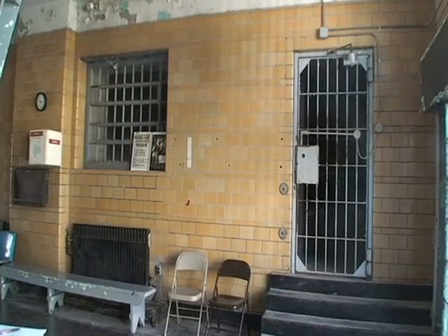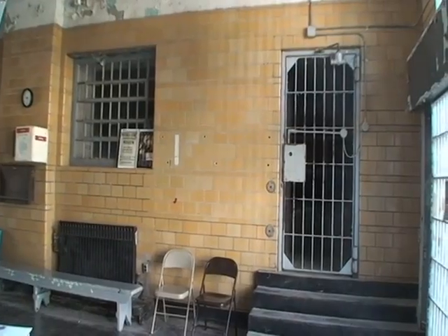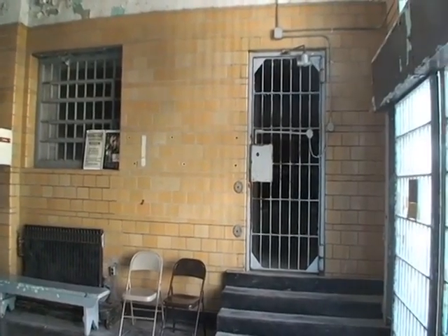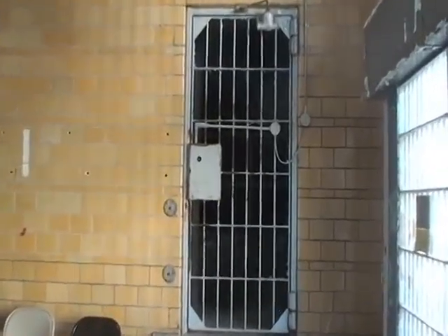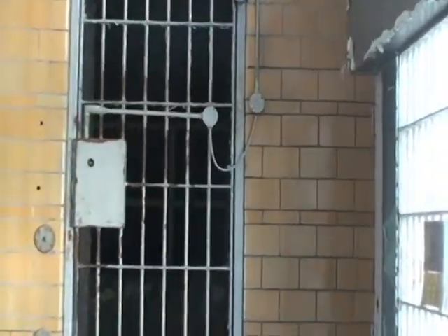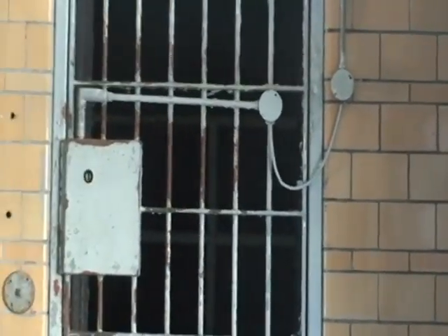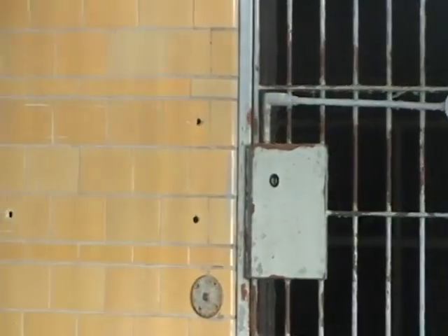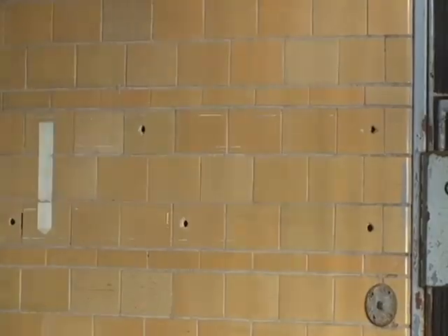Another building component to keep in mind is the brick materials and floor materials, concrete, asphalt materials. If you get into an older building, and it's got glazed type bricks such as this one, typically if they actually do an analysis on those, you'll find high contents of lead and other metals. So that needs to be taken into consideration as to, are they going to use these on site as clean fill, or what kind of work practice is going to be used, or how they need to be disposed of. That may need to be handled as a special waste underneath the solid waste program.